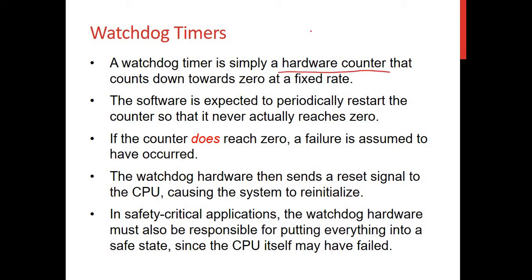Okay, so if you recall in your Arduino Uno or your Atmel 328, you do have timer blocks. You have timer 0, timer 1, and timer 2. These are all specialized hardware timers that we have used in EPP and so on for our PWM generation, and doing some interrupt based counting. Similarly, a watchdog timer is also a separate hardware block.